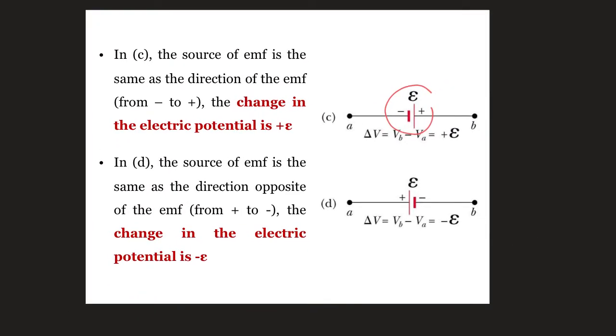For this one, we only focus on the potential difference of the power supply. So here you are going to focus on the assumption loop. Your assumption loop is the one that decides the sign of your voltage, whether it's positive or negative. For example, if your assumption loop is moving from the negative terminal to the positive terminal, please look only between the terminals. Please don't look at the circuit. That one is going to be different. Only focus between the terminals.